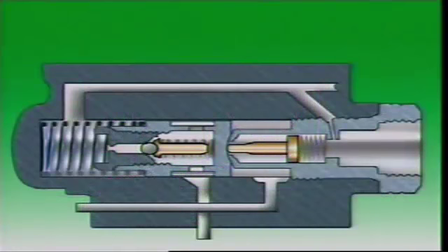During slow cornering or when parking, pump speeds are normally low. There is less demand for fluid flow, but to provide the required assistance, high pressure is needed. Discharge ports direct the fluid to the outlet and then to the steering gear. The outlet fluid pressure is slightly lower than the internal high pressure coming from the pump.